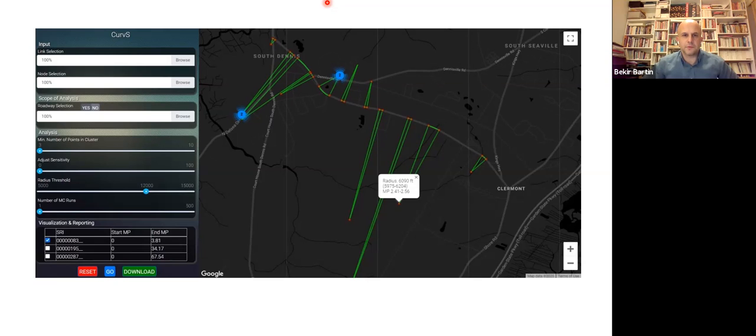You mean the reverse curves, I believe. How can you obtain the S curves or complicated ones? Me obtain or detect? I believe you mean detect. It detects the S curves because I use the curvature value, among other explanatory variables. So the curvature value will be different. The second order derivative will have a negative value or positive value, so it can identify the S curves. But the complicated ones, as Tang asked, the spiral curves, no, it cannot.